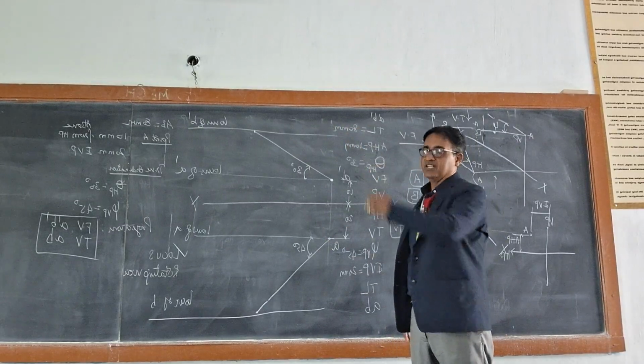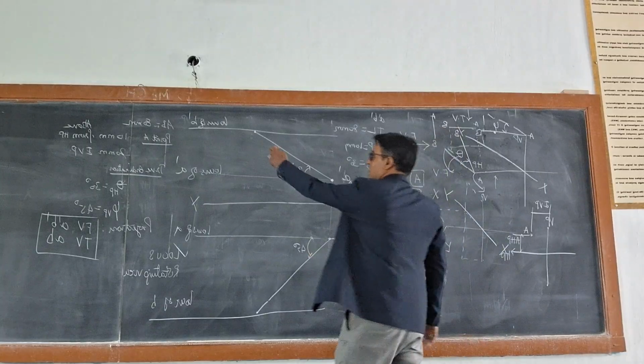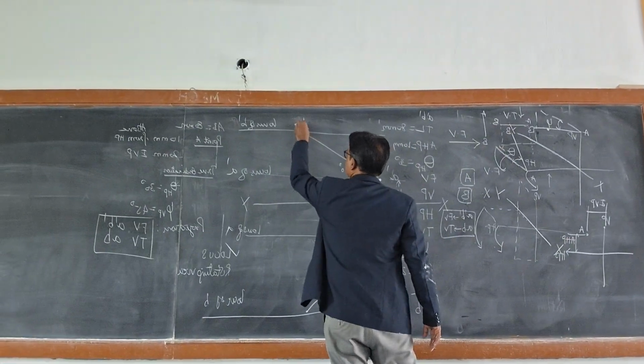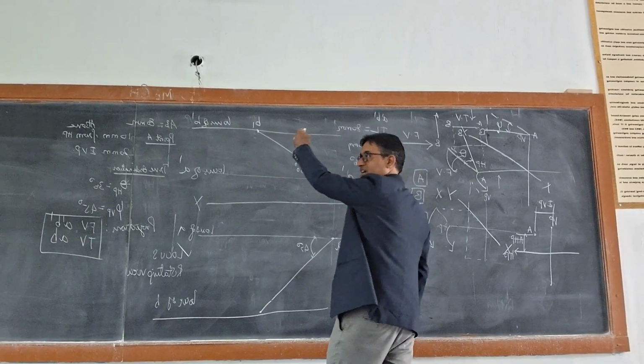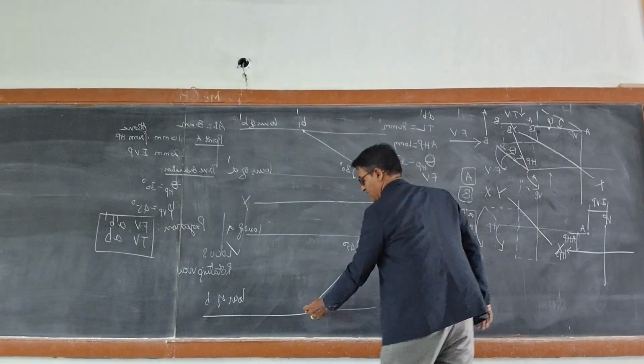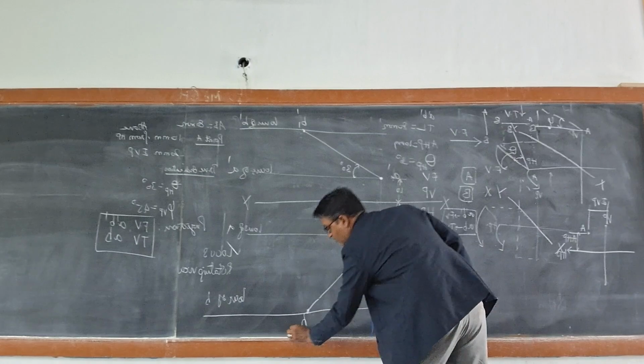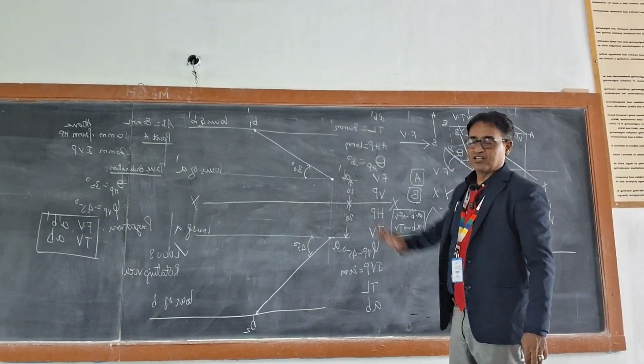Then how to construct or how to find the B dash and A dash. So after giving a notation to this, say I am giving it as B1. Since it is above XY, it is a front view, therefore you have to add a dash. So B1 dash. Similarly here I am just giving it as B2. Here no dash because it is top view.